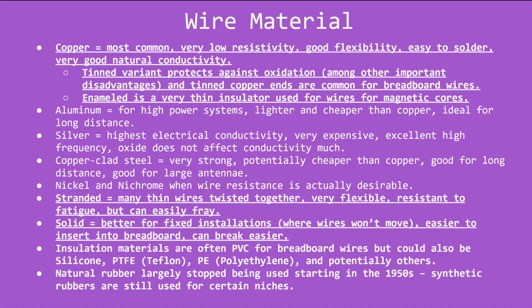We've already talked about stranded and solid. You know, stranded is many thin wires twisted together. It's very flexible. It's resistant to fatigue, but it can easily fray. Solid, that's better for fixed installations when you're not going to move the wires too much. It can be easier to insert into a breadboard though, but it can break easier.